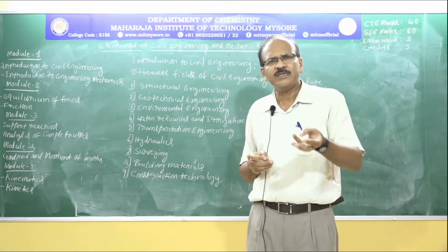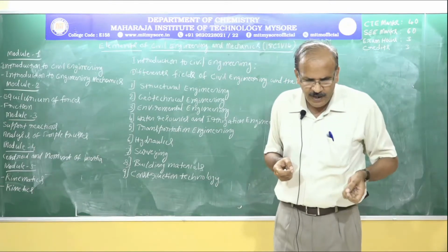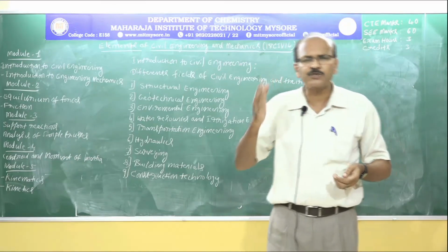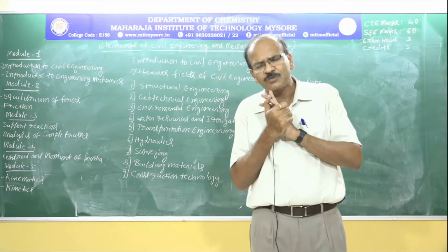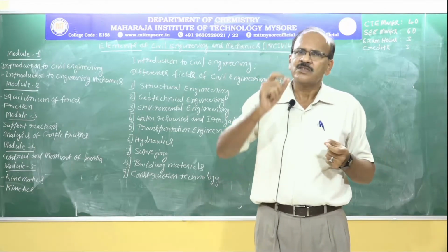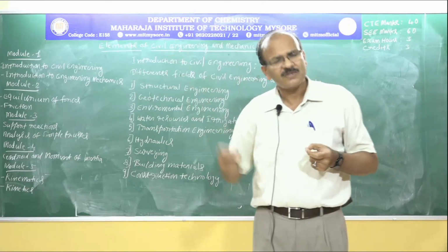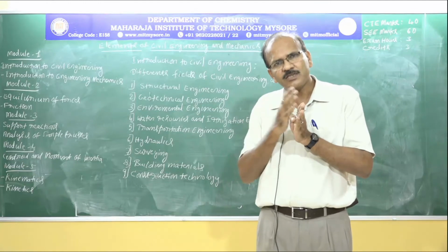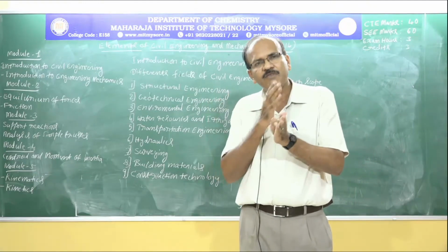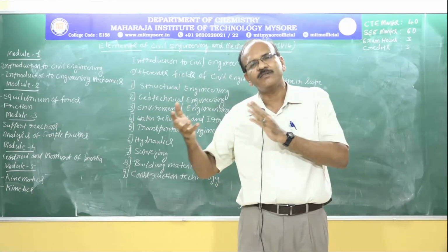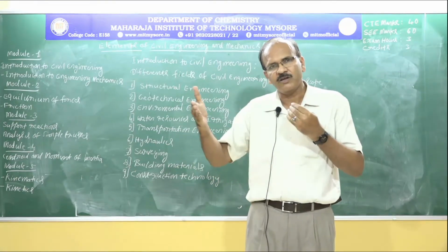There are different properties like the cohesive property and the internal friction property, and we also study the grain size distribution of the soil. Grain size distribution is nothing but that a soil contains different soil particles of different sizes, and if you take any size between specific sizes, say for example soil between 200 micron and 600 micron, 300 micron and 600 micron.